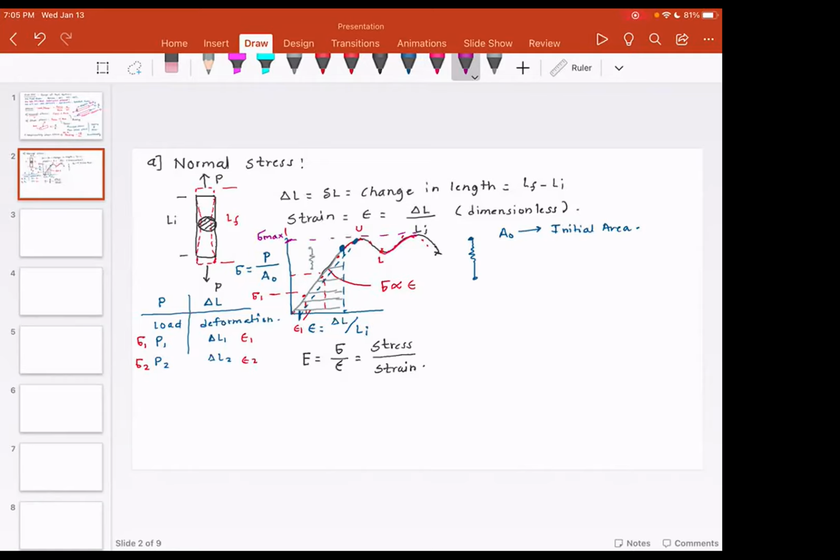But please note, the material is plastically deformed. Now at this point, you are going to observe that for a ductile material, the area will be reduced. So this reduction in area means instantaneous increase in the stress. And the instantaneous increase in stress at that reduced cross-section area exceeds the failure stress, which means it exceeds the strength of the material. The strength of the material is the maximum stress the material can withstand.